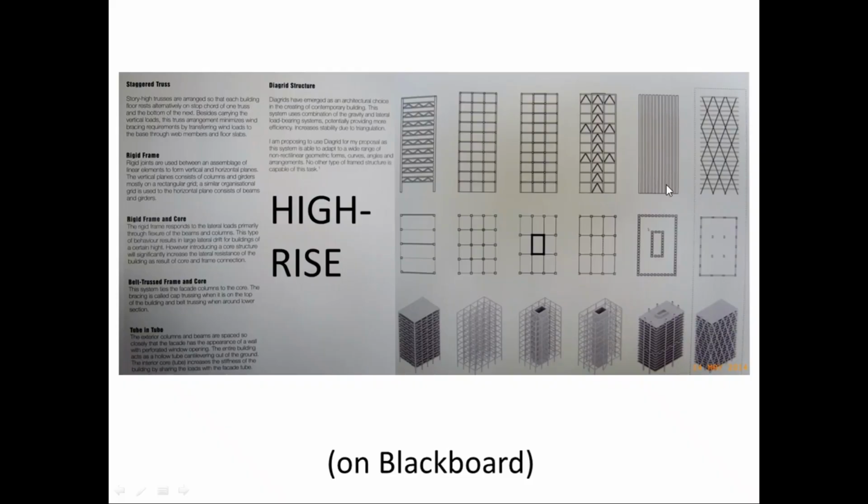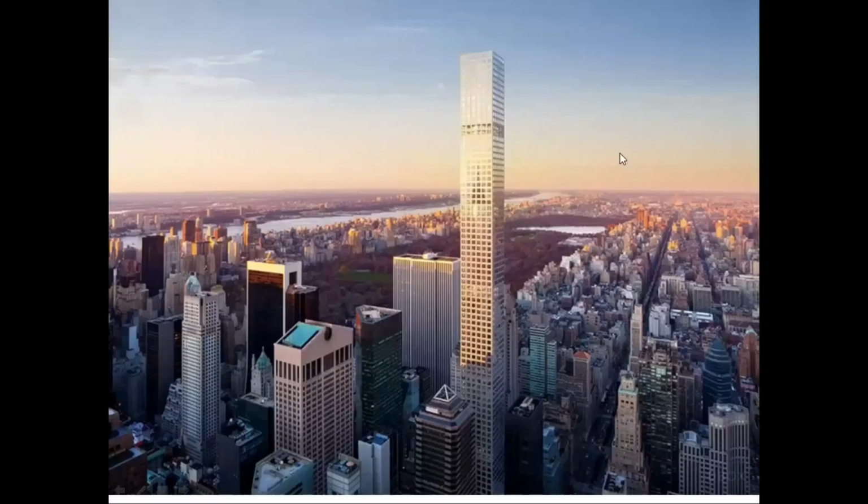There was progression until the whole building collapsed. This is, if you like, a kind of solution to this. So it's an exoskeleton, it's continuous forces around the outside of the building. It doesn't rely so much on the central core with a series of outriggers, which we now know could fail, because if there was an impact at this level of this building, because there is a continuous triangulation wrapping around the whole structure, you could not get this sort of progressive collapse. Of course, what could potentially happen is that the whole thing would just fall down as one piece. It would topple. But let's not go there.